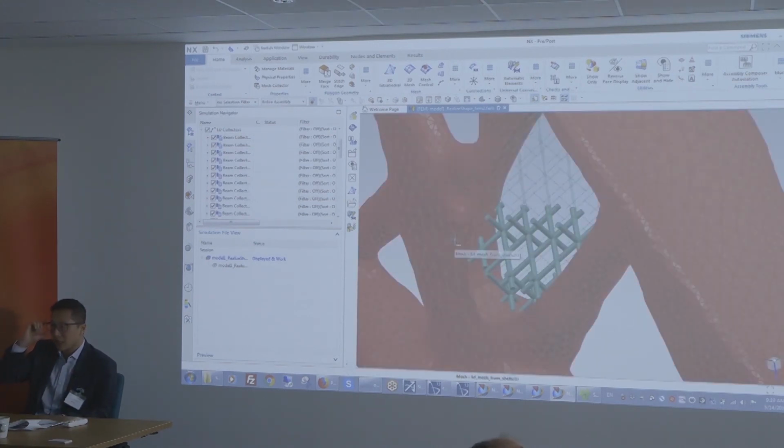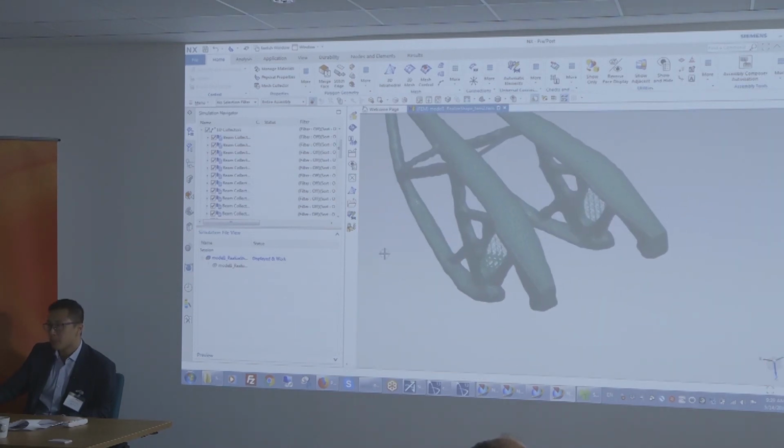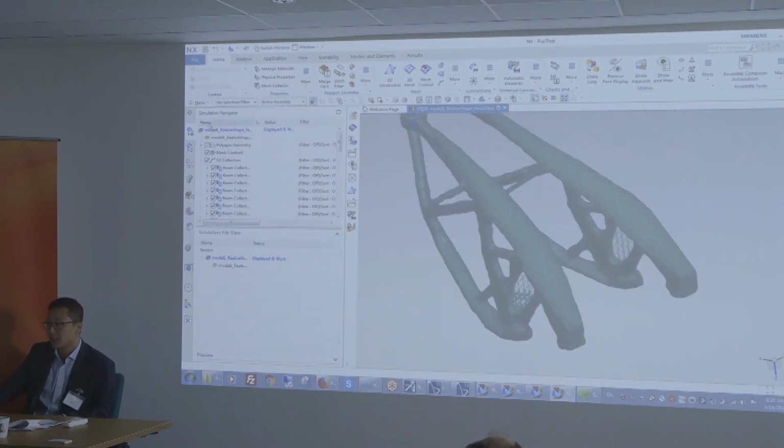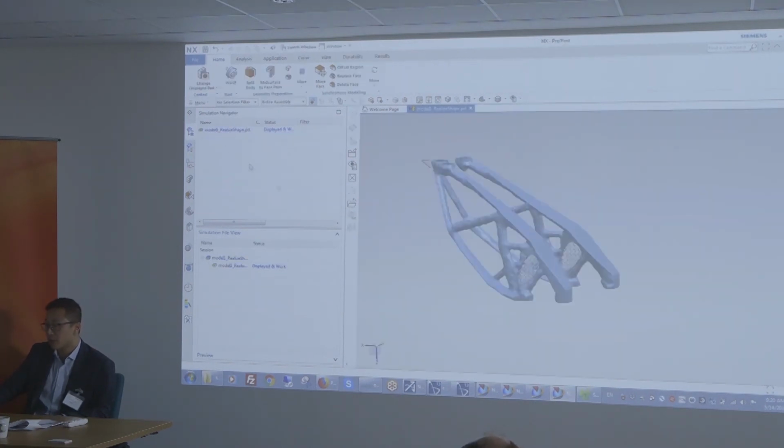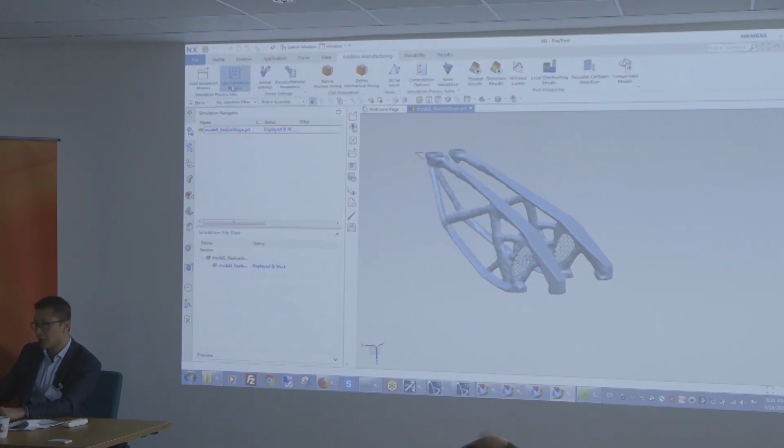But if you wanted to, say for example, STL this out now to 3D print it, does it need to go through another conversion process? And would that convert into a nice clean STL? So if you want to go directly to additive manufacturing, you wouldn't even go to the FEM level. You'd stay in the original CAD, and directly open the application for additive manufacturing, which will take into account those. You would go directly in that environment. It would not represent those beams as 1Ds because that's only for FEA purposes, right? Right. Okay.